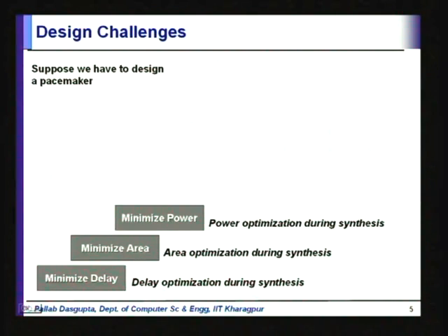right. So, power optimization is an interesting thing, and the corresponding verification problem is to make sure that you are not exceeding your power budget at any point of time. So, there are new specification languages like UPF and CPF which are used to specify the power intent of a chip. Okay. These are new standards that have come up.